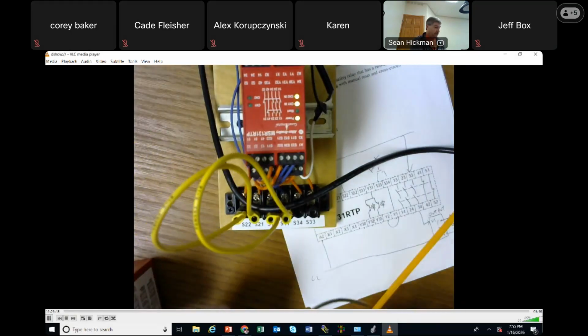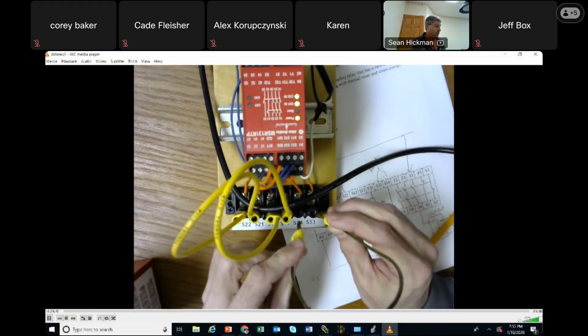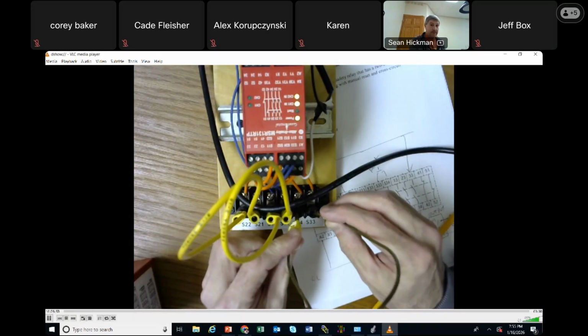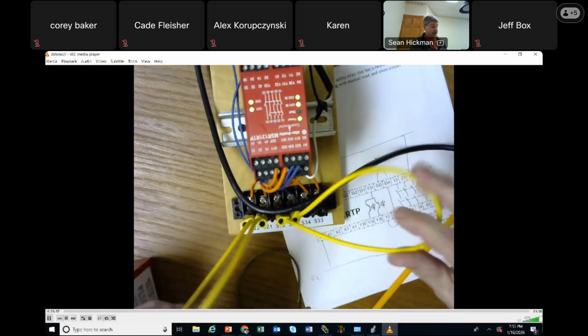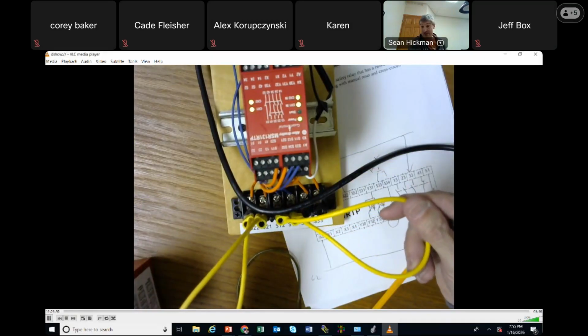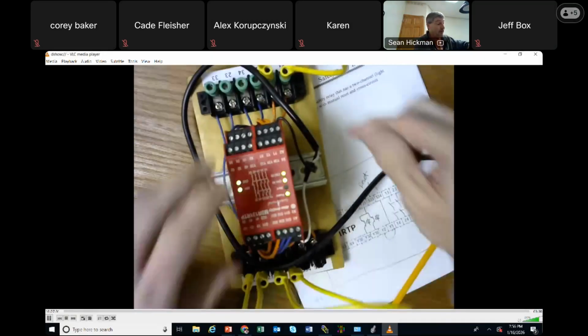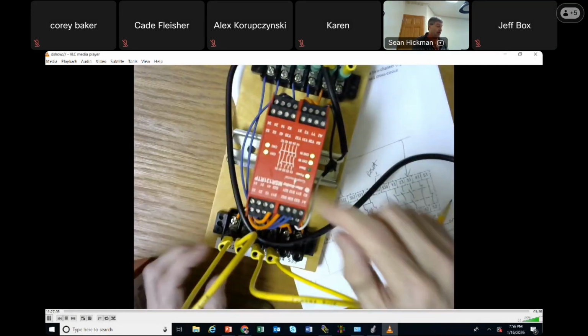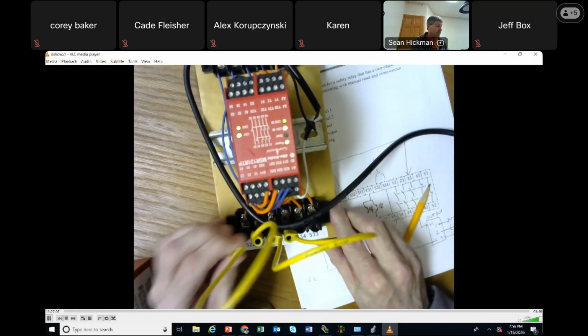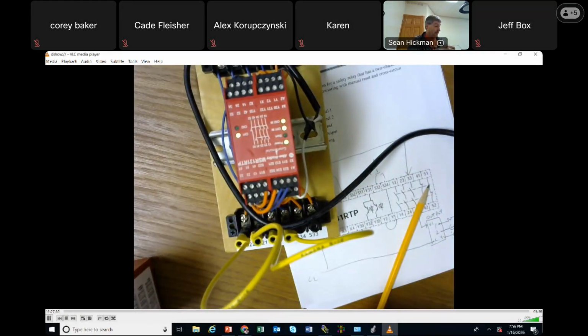So I'm just faking a button here. Watch up there. Here's my reset. Ready? It reset. So my e-stops are normally closed, so I just jumpered them like they're normally closed because that's what it is. And there's no monitoring on there. So I jumpered it like it's closed. And then boom, I can fake an e-stop right here. Fake an e-stop. Hit the reset.